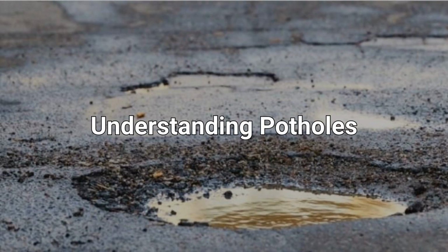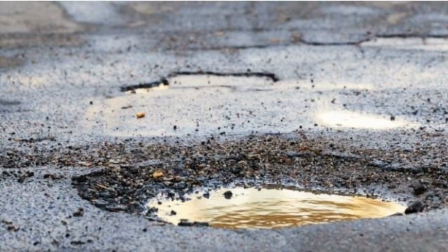Understanding potholes. Bowl-shaped depressions in the pavement surface penetrating all the way through the asphalt layer down to the base course are called potholes. They are generally circular, with diameter less than 30 in, 750 mm, and depth greater than 3/8 in, 10 mm, and have sharp edges and vertical sides near the top, as shown in Fig 8.7 (ARA, 2015). Serious vehicular damage can result from driving across potholes at higher speeds.